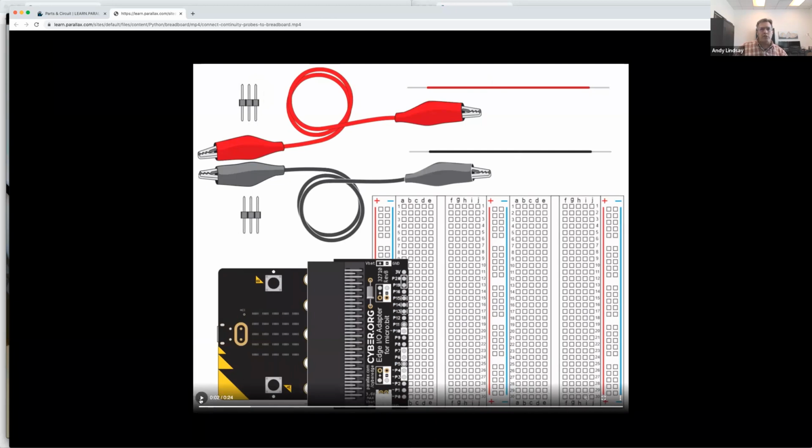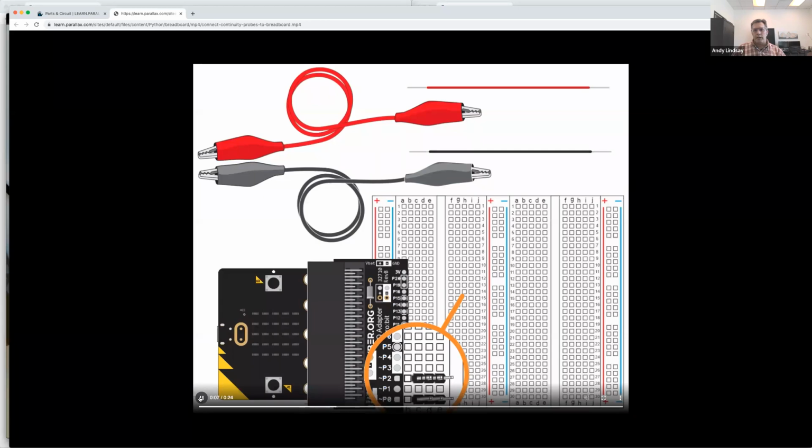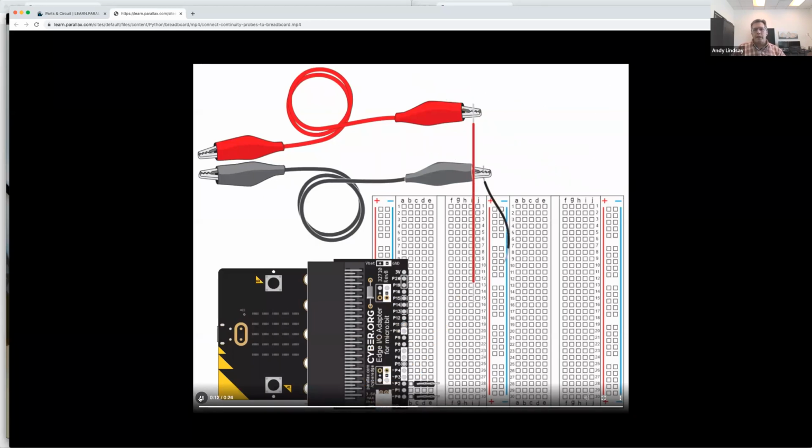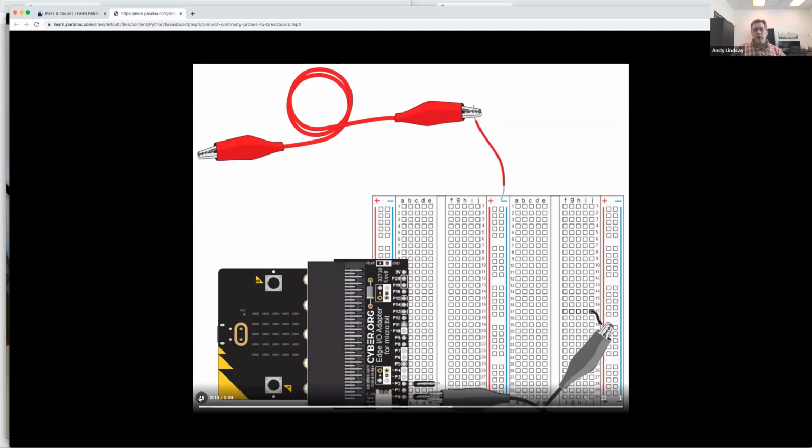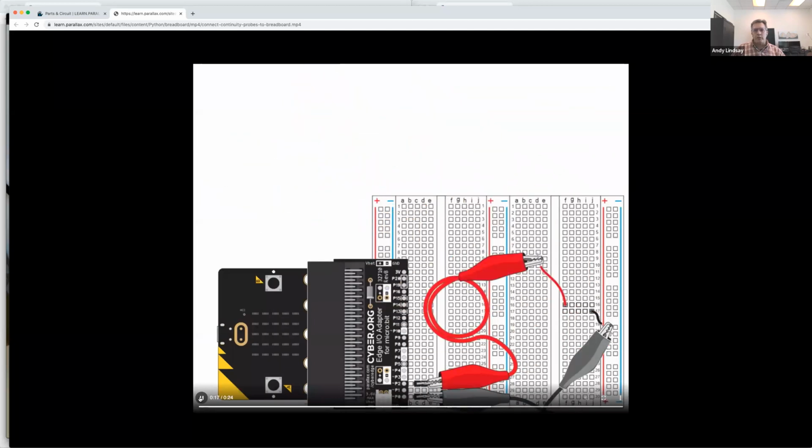And then the 3-pin headers are going to plug in on rows 30 and 28 right next to the P0 and P2 pins on our adapter. I usually like to leave one socket. I like to plug the 3-pin headers in the rightmost part. And then we use a magnifier to make sure that the students get that right. And then we'll use our alligator clips to grab the 2 jumper wires.